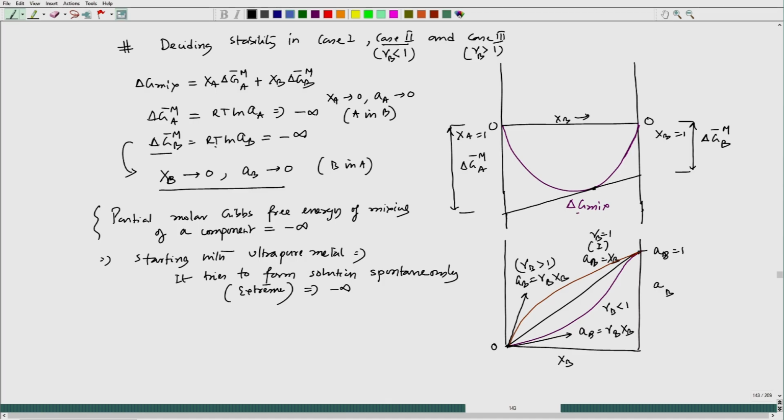Okay. So, this particular information would be very critical when we try to go to a situation where alpha is a very high positive value, or we can say delta H_mix by RT is a very high value, and there, in some composition range in between, there could be a possibility that delta H_mix by RT can actually have a higher value compared to the mod of delta G_mix by RT ideal, because delta G_mix by RT of a non ideal solution is nothing but delta H_mix by RT plus delta G_mix by RT ideal, and delta G_mix by RT ideal is nothing but minus T delta S_mix, which is the same for both ideal as well as non ideal.